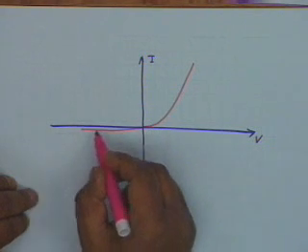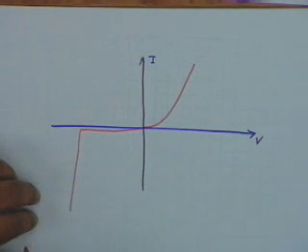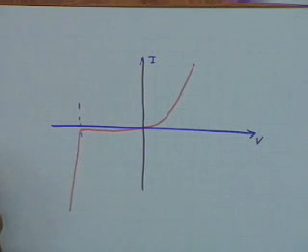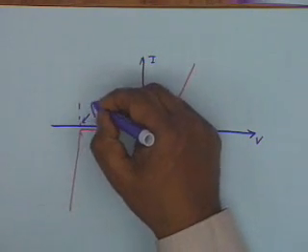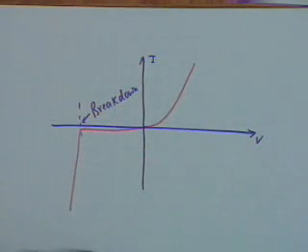It becomes almost constant, and then suddenly at some point on the reverse voltage, the current starts increasing drastically as the voltage is increased. A very small increase in reverse voltage causes a very large increase in current, and this is called the onset of breakdown. It is as if the diode cannot resist any further, it breaks down.